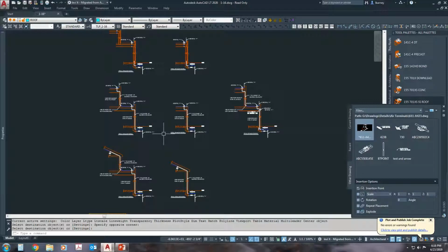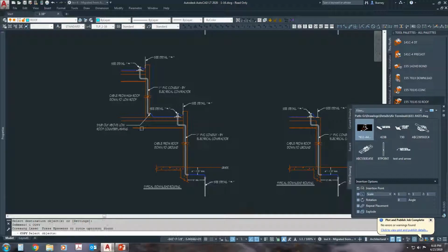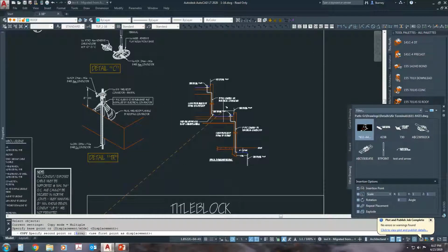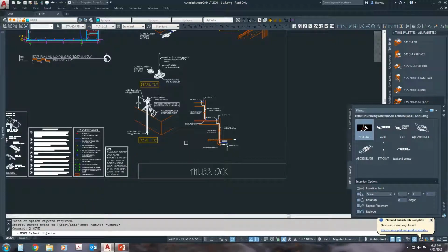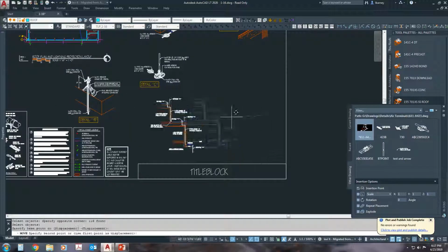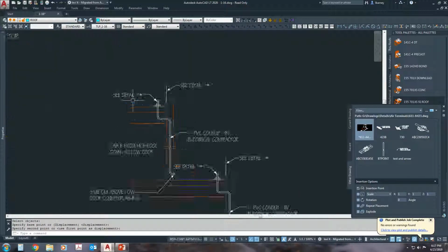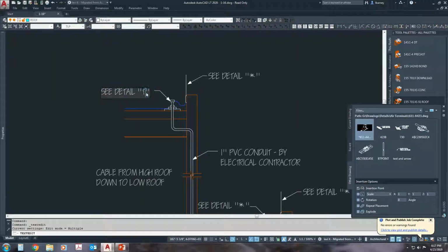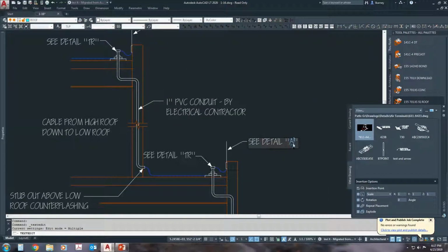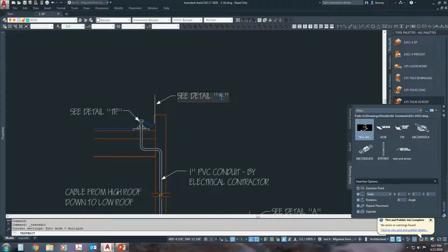Then we need to pick out a section that depicts how the cable is getting from the roof down to ground. So if this was a steel building, what we could end up doing is utilizing the building steel as the path to ground. However, since this is a concrete building, we are going to have full cable all the way from the roof into the earth. And this depicts the detail T and T2 on the plan.